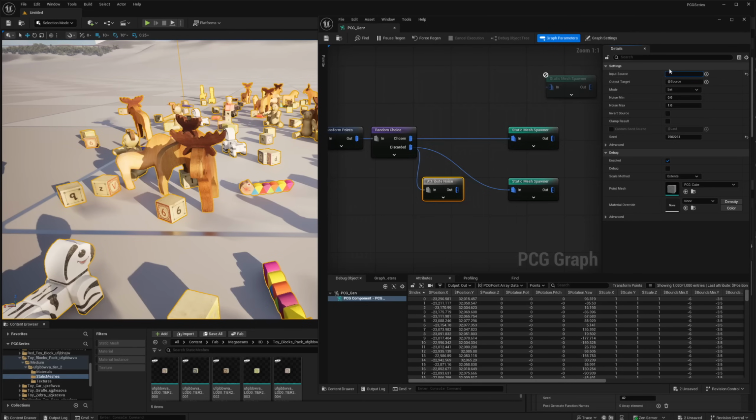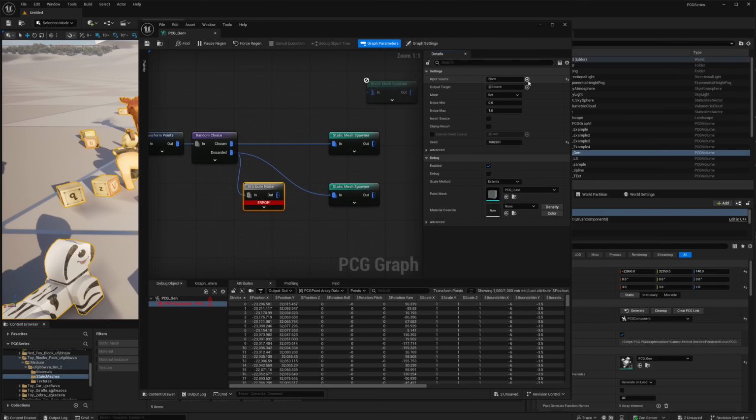And of course, you can use the interface in Unreal Engine for doing this by clicking here on the plus sign, then choosing the point, and this will list the values that the point has by default. For example, we need now the rotation. Then again, plus sign, and this time instead of choosing the attributes, or properties as they call them here, we will add an extractor, and this will be for our rotation. That's why we are choosing this rotator, and here you can find this roll.